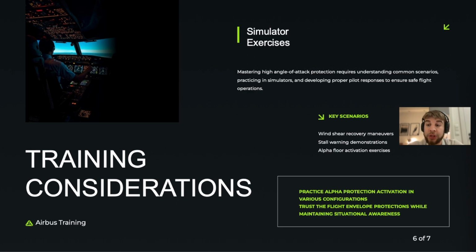Proper training is essential to fully understanding and effectively using angle of attack protection. Pilots should practice scenarios such as windshear recovery, stall warning demonstrations, and alpha floor activations in simulators. It is important to recognize when protection is active and respond correctly. Pilots should trust the flight envelope protections while maintaining situational awareness and control of the aircraft. Mastering these concepts ensures safe and confident aircraft operations.